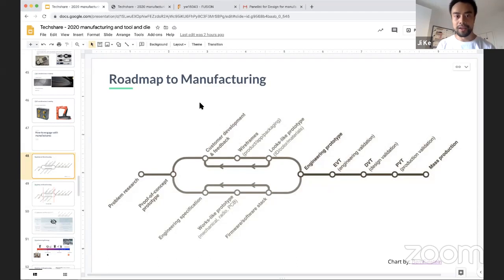Okay, the next one. How difficult is it to injection mold parts which have features with a width of 0.8 millimeters? I do not know without looking at the design. There is a lot more in play than just the feature width. It includes the uniformity of the plastic. Is it only that part that is 0.8 while everything else is 2 millimeters, or is every single feature 0.8 millimeters?